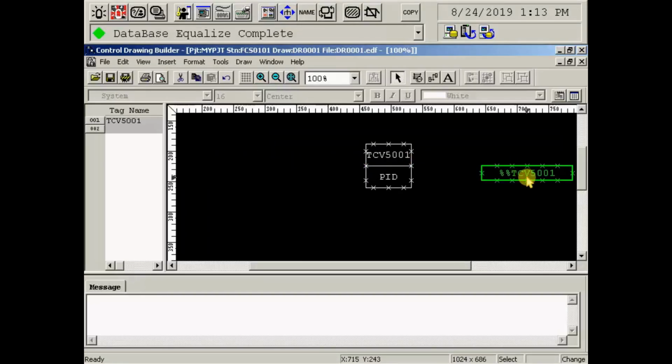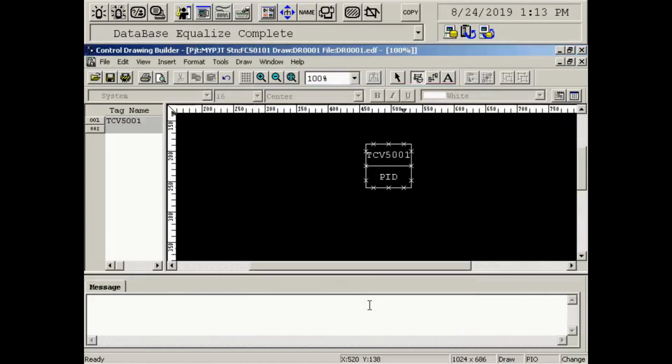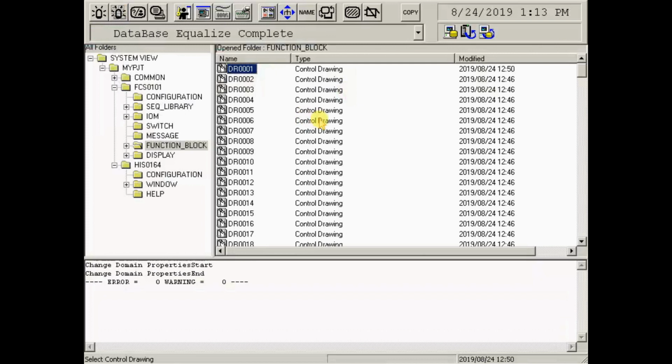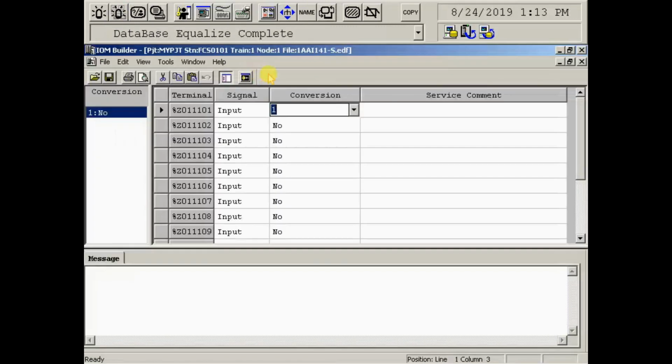For this purpose, we need to delete the old inputs to the PID controller, add new PIO, and we also need to provide the actual or physical addresses for analog input and analog output to the input and output of the block.